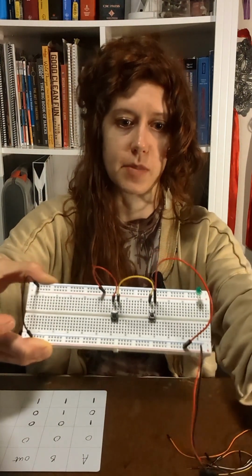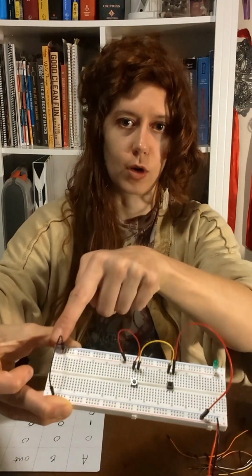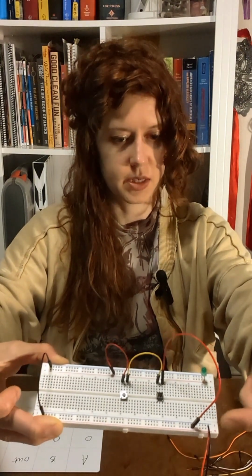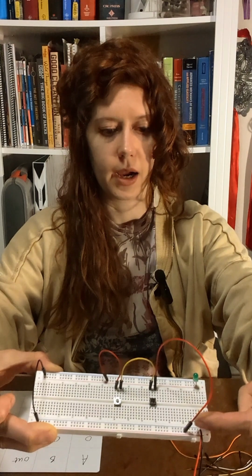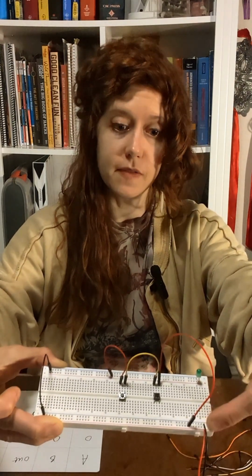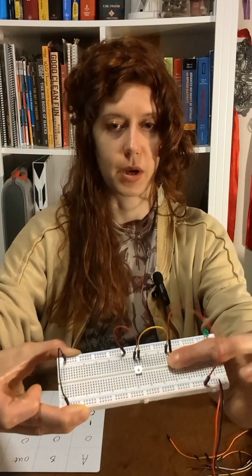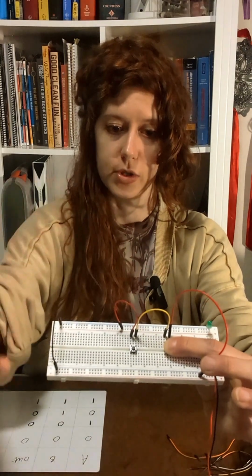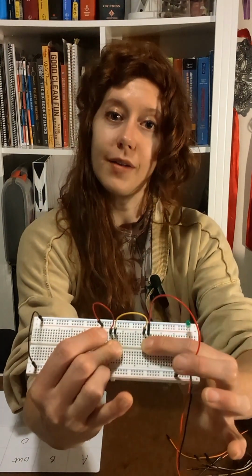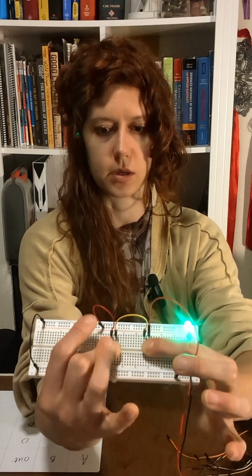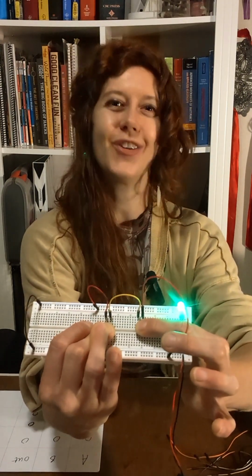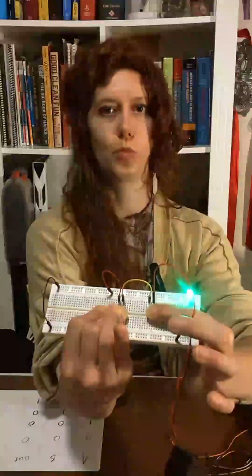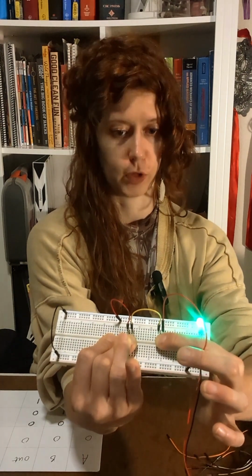And here you can see if we trace the path of the electricity, the ground is connected, or the negative side of the circuit. And we have the positive, energy is flowing from the positive side of the battery through this wire. When I push this button down, energy can flow out the other side of the push button through the yellow wire to the second push button. And then the electricity can flow from the yellow wire through the push button to this red wire and complete the circuit, and our light turns on. Yay! So this is a series circuit. There is one single loop for the electrical current to flow.